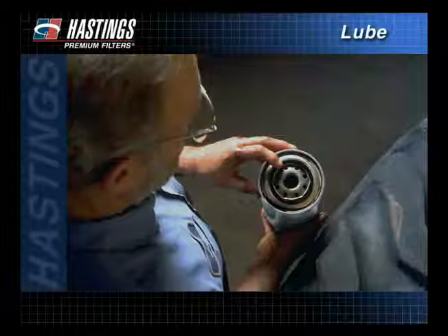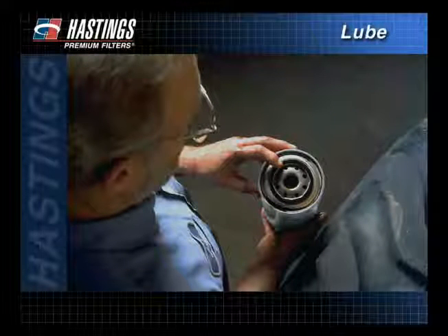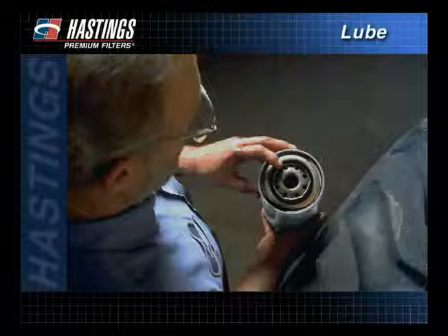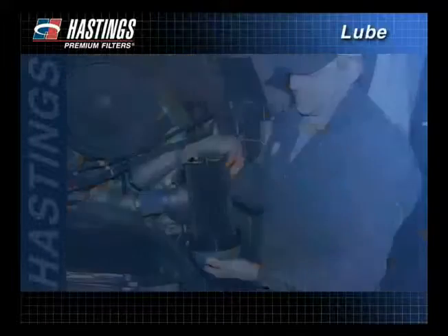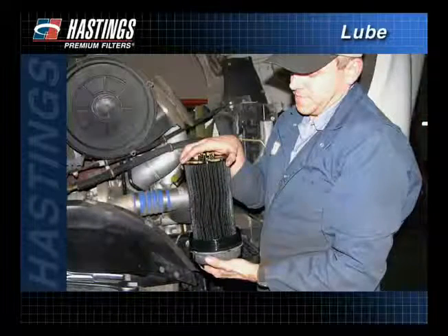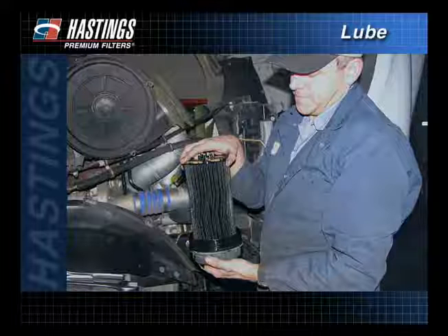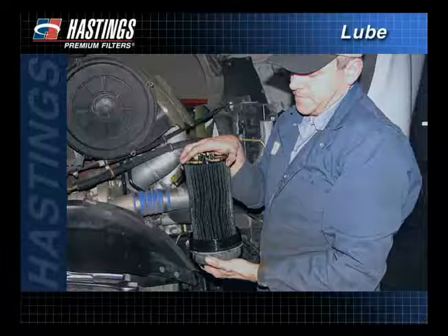Even with proper oil and the best filter system, problems can occur. As part of your maintenance practice, occasionally inspect filters to detect the beginning of serious engine problems. With a cartridge-type filter, the analysis is easy. Simply take the filter out and look at it. Spin-on filters, however, need closer inspection.